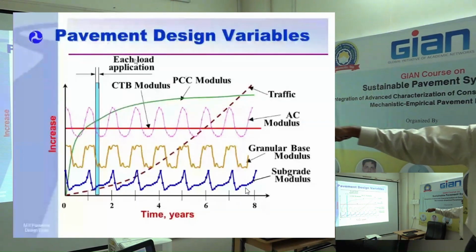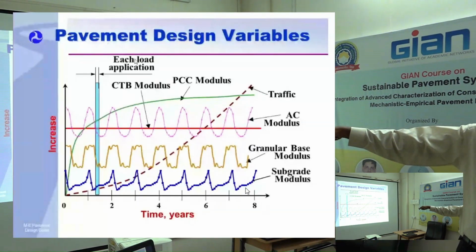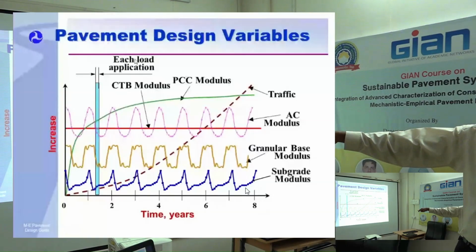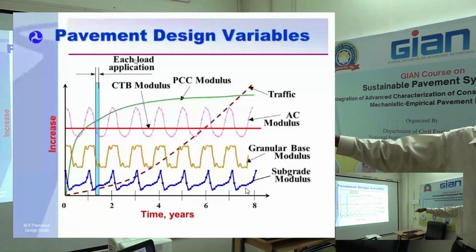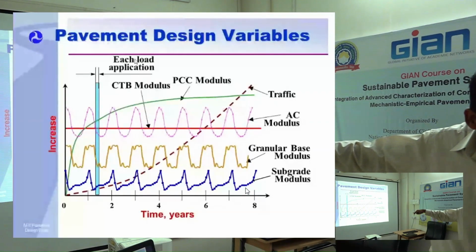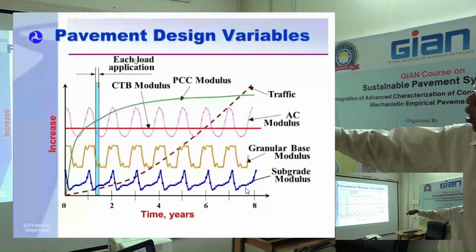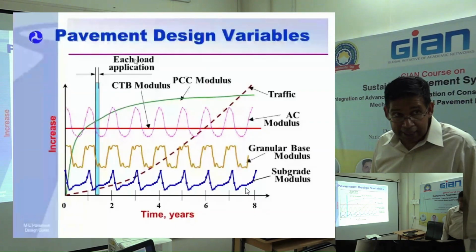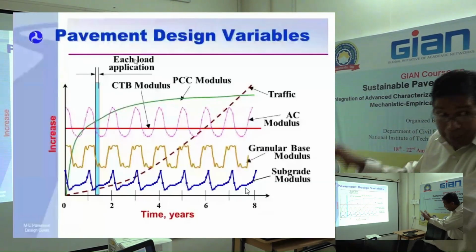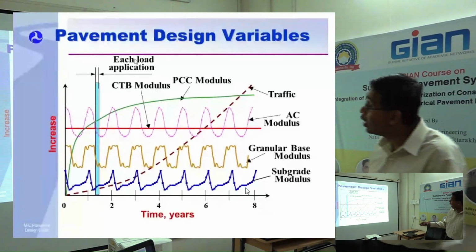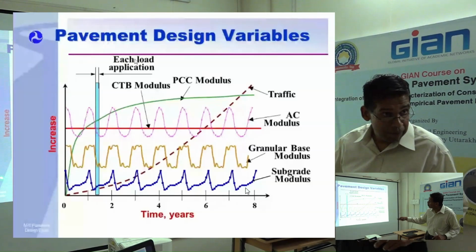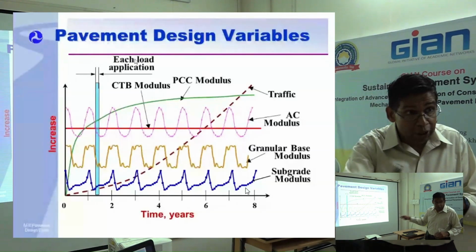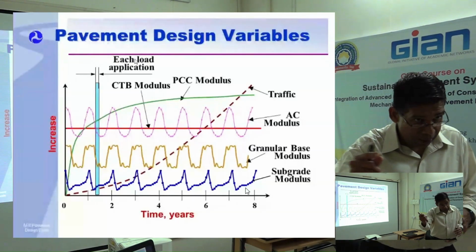Let's look at asphalt modulus. January, very cold. Come back to summer, very hot. Asphalt is very, very soft. Modulus is very low. Come back up, goes down. You got it? Everybody with me so far? This is the framework of MEPDG. You have to only put for 1 year. Everything automatically gets repeated for the next 19 years. Everybody with me so far?